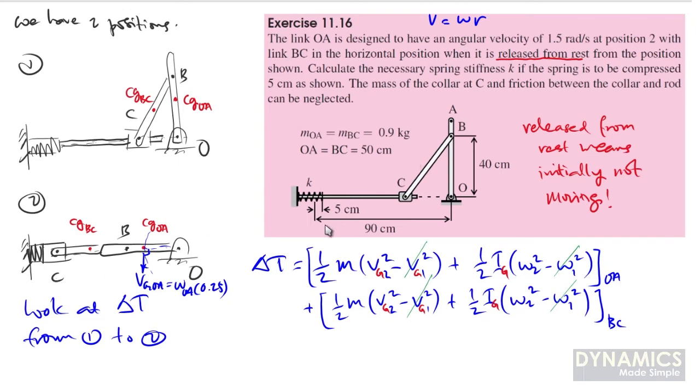If BC is moving in general motion, we have two approaches to do the velocity analysis: either using the I, the instantaneous center, or using the relative velocity equation. In this case, the easiest way is to use I. So how do we find I? We know point C is moving in linear motion, or translation motion. So the line of velocity of C is known. This is the line of velocity for C. The line of velocity for point G is also known here.